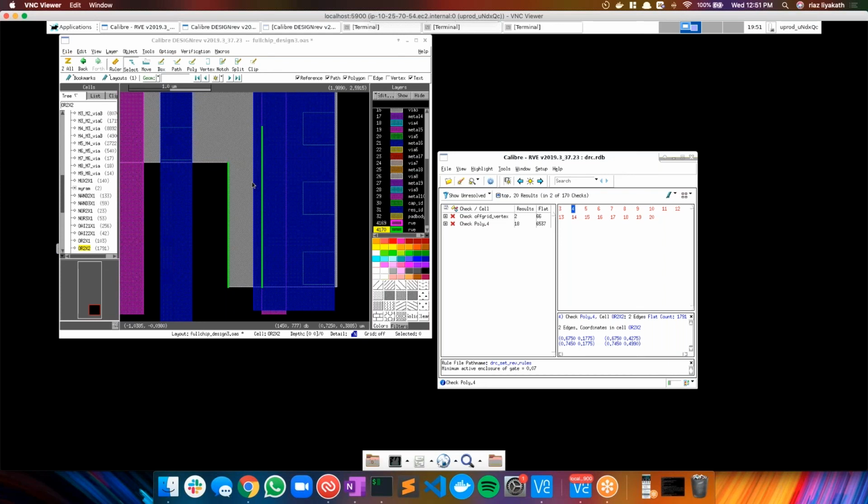To summarize, what we saw today was how you can run Calibre DRC end-to-end on the Rescale platform. It contains 3 pieces. First, you spin up a storage device to set up your environment. Then you can run many batch DRC analyses for different cases. And once you have all the batch analysis databases, you can open RV interactively and look in real time to identify where the error is, and then fix those errors to continue in your design process.